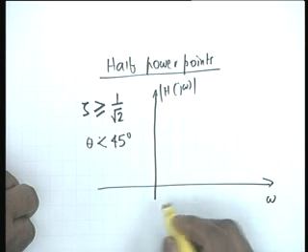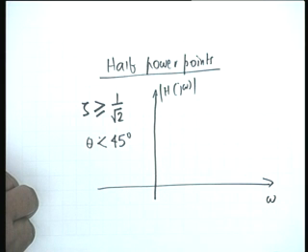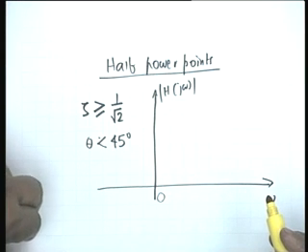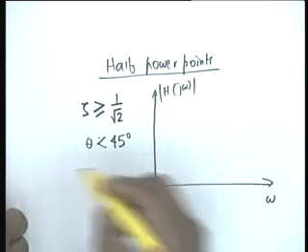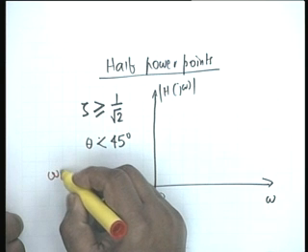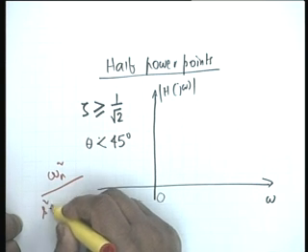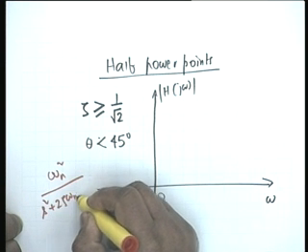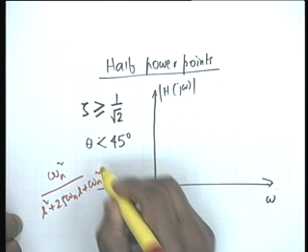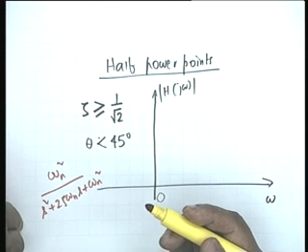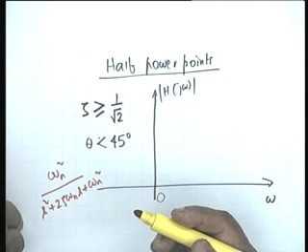What is the DC response? The response at 0 frequency, well, you remember the transfer function, s squared plus twice zeta omega n s plus omega n squared. So at s equal to 0 it is equal to 1, isn't it right?